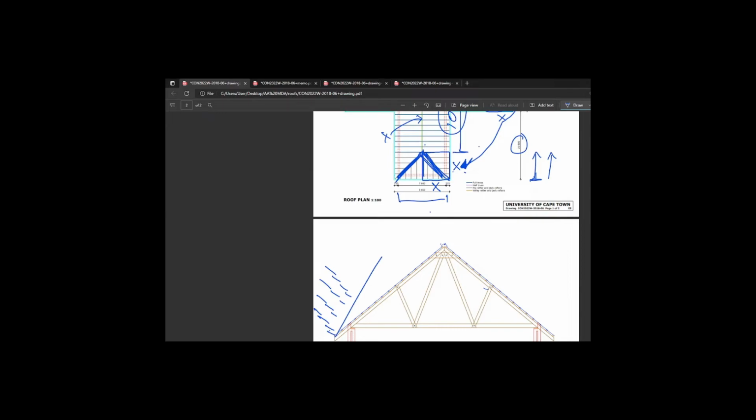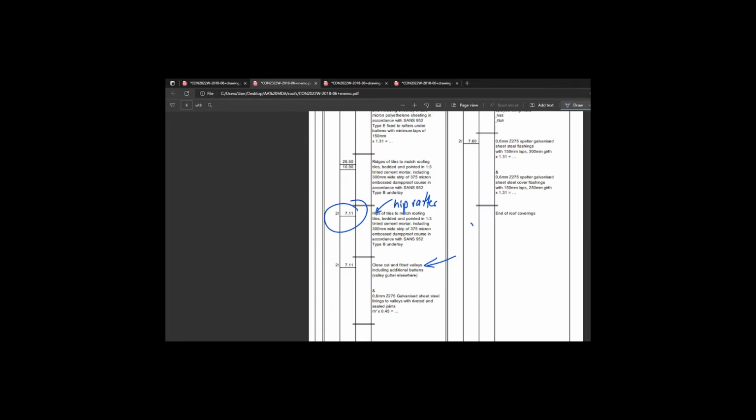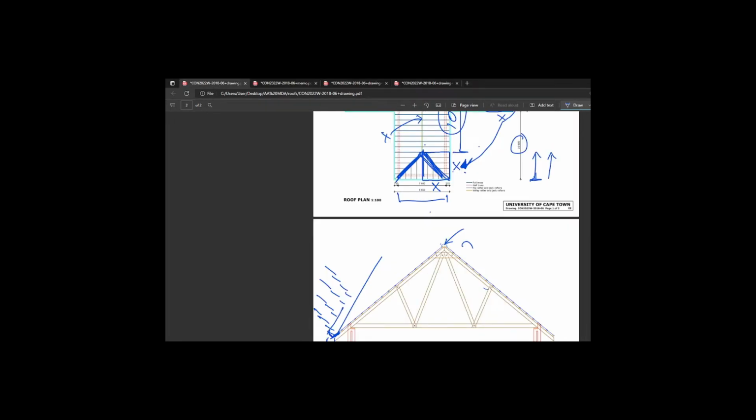We've got a ridge tile, it's this shaped. Now, you might say, why don't you put a ridge tile like this? And it is unnecessary because what you do is rather put a thin sheet of steel. The description specifically is galvanized sheet steel lining. Okay? Thin piece of steel that runs along. So they obviously have to fix it early and then lap the tiles over it. Okay? And so when the water runs down, it bounces and it goes past the last tile actually into a little steel, let's call it valley lining, and then after that it runs along the lining and out.